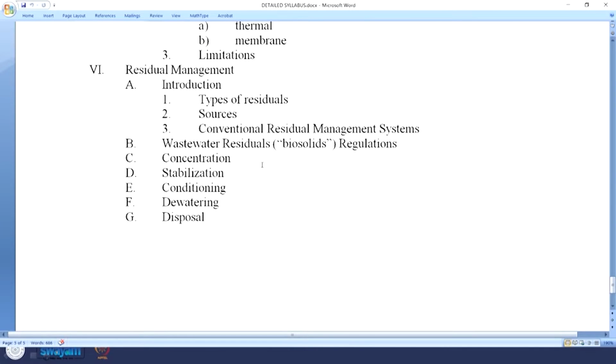So, in the general overview, we are going to look at material balance to understand how I analyze these systems. For example, I want to design it. Design meaning, first let us say I want to know the size or the volume that is required of either the water or the wastewater treatment plant. So, how do I do that? I need to then be able to understand how much is coming in and at what level can I send it out, and then how is it being transformed within my particular reactor or treatment plant. And then using the principles of material balance or mass balance, we will be able to get it done, right.